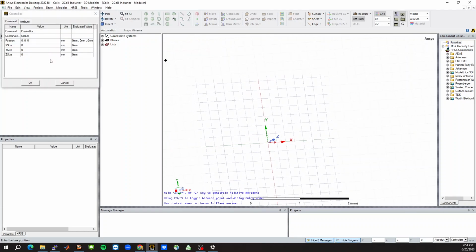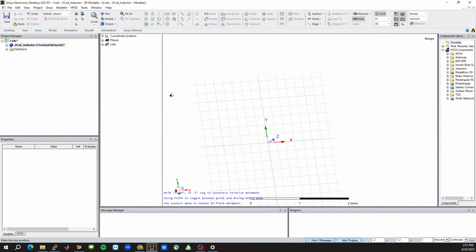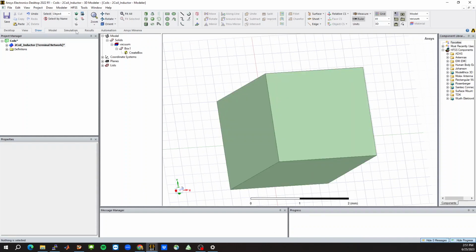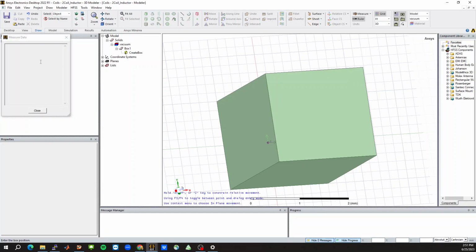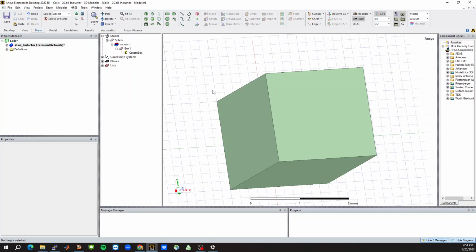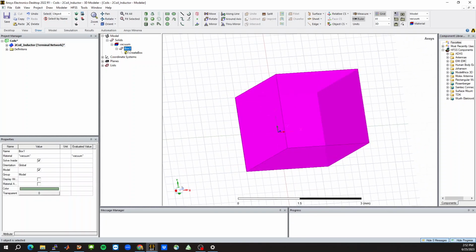So click on the box, and you can either hit F3 to remove the prompt that came up in case you want to draw it by hand, or if you want to draw it using the prompt, then every time you hit a box and you don't get the prompt, you can hit F4. Okay, so let's take this box. I'll call this silicon.